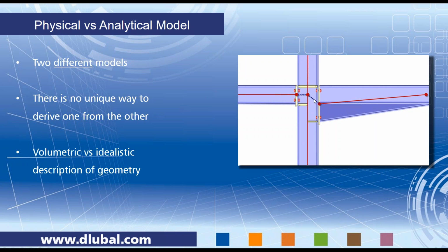So some software has eccentric links that can be used, and they don't actually need a separate member to connect those gaps here. Or in a simplified model, we can just ignore this eccentric haunch here and just have a straight member. So there are different ways how we can do it, and obviously it needs a little bit of help from the engineer to decide how they want to build that model.